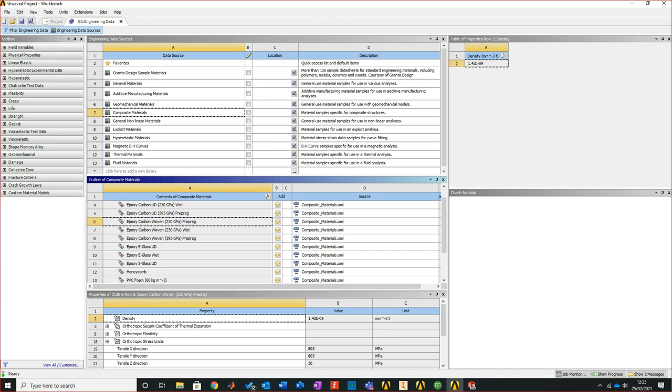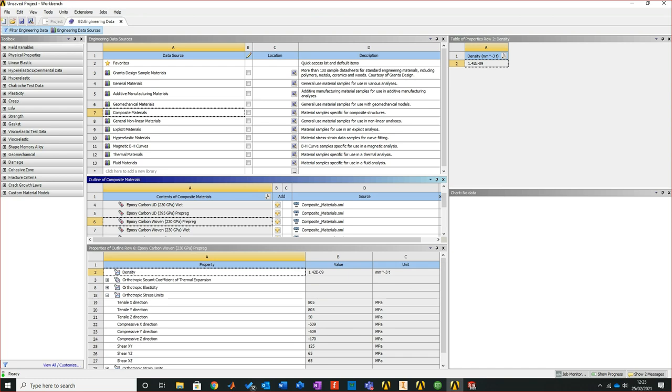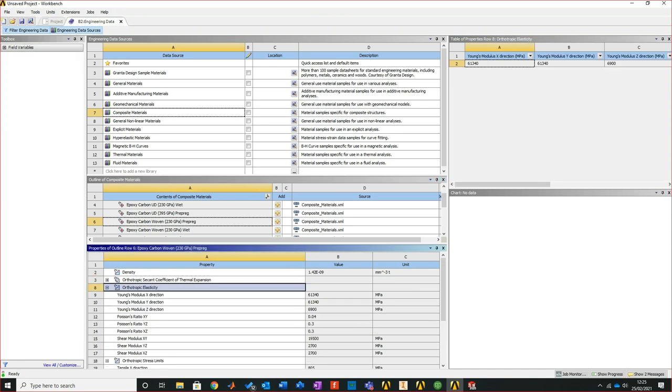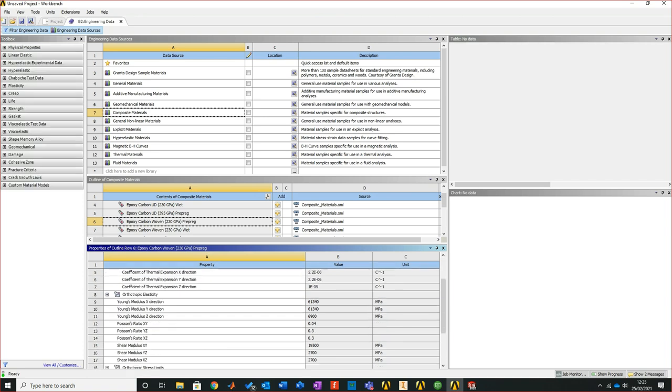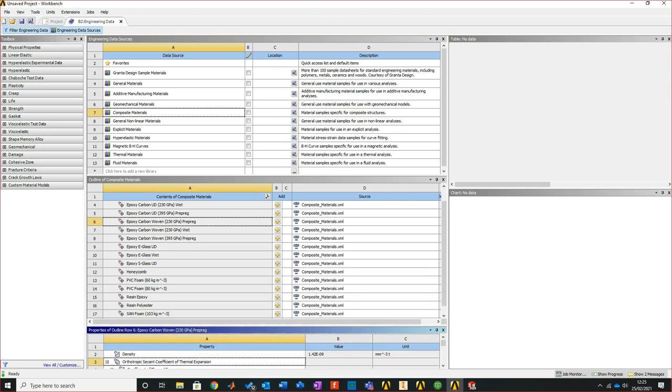But again, what this does do is show you how the tensile behaviours, compressive behaviours and shear behaviours are set up, or even when you come to your elasticities and how these are set up. It shows you how carbon needs to be set up, which is great. But what I want to do is assign a woven pre-preg 230 gigapascal epoxy. By clicking on the tab, I've added this into my library, and beneath here you can see we've got some resin